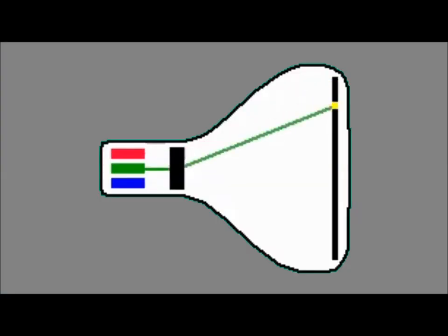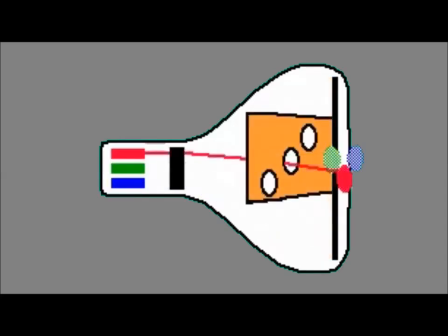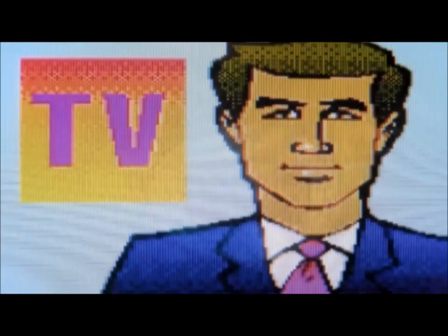At the rear of the picture tube are 3 electron guns. These beams contain the picture information for the color channels. These hit the colored stripe segments, and the tube is designed so that each beam can only hit segments of its own color. A shadow mask prevents each beam from striking the other stripes. Because the colored segments are so small and so close together, the effect, when viewed from a distance, is of 3 superimposed images in the primary colors.